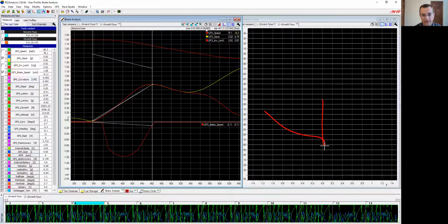So when I'm looking at this time delta, I always want to look at the fastest braking zone on the track first and work my way back from there, because the fastest braking zone is the one where it will make the biggest difference in terms of getting this right. Because you're traveling at a much faster speed, that half-second delay means you've braked that much more early, right? So the faster you're going, the bigger difference this makes.